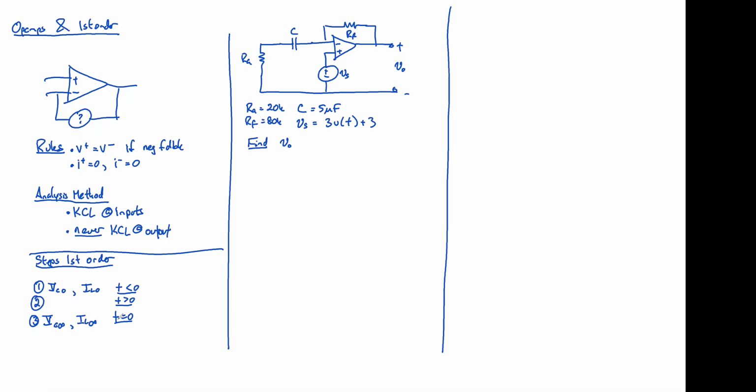Is I 0? No. That's your very first step, is to find I sub L or V sub C, depending upon if you've got a capacitor or an inductor. And that's for time less than 0. So that's that DC steady state. And then it's also DC steady state.